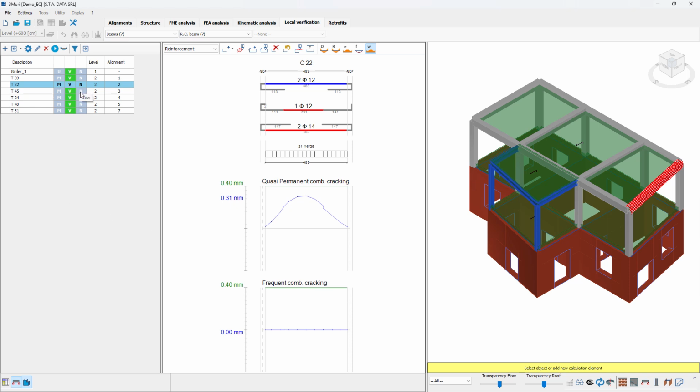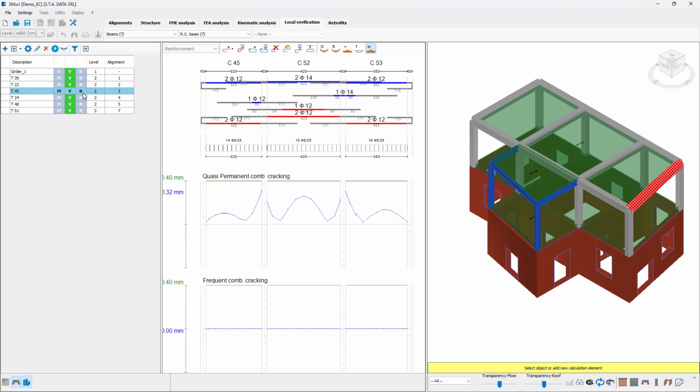Lastly, another option that I have with the reinforced concrete beams is that if I have imported a reinforced concrete beam from the structure environment and I decided to do some changes on the structural rebars, I can just go ahead and export those rebars that I've just modified into the structure environment. So we can do this very simply by just clicking on this icon over here, and a message is going to appear that the export was successful.